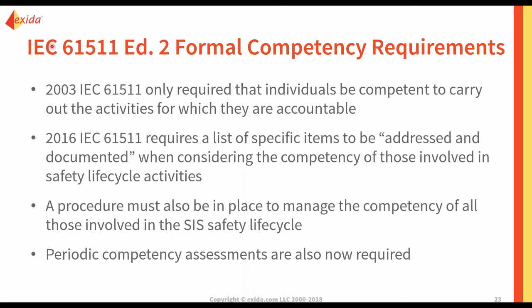And then also looking at the competency requirements. And so in the newest version of the IEC 61511 standard, these requirements have been further enhanced. And so now, in addition to just requiring that the individuals are competent to carry out the life cycles for the activities for which they are accountable, it's also requiring a specific list of items to be addressed and documented when considering the competency.